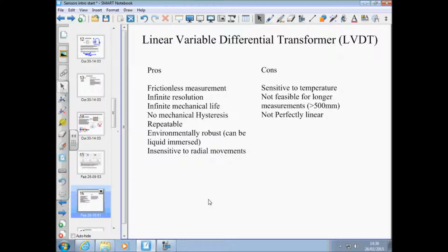They use one of these LVDTs to control the opening and closing of that, because you're probably not moving it more than about 2 mil maximum travel, but these will do that. You can get quite a big variance in output for quite a small movement in distance.